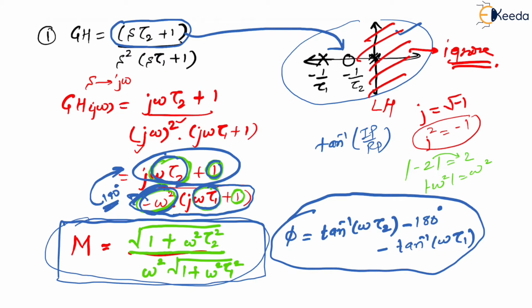So if you just see here, 0 is closer to the origin. What does that mean? If 0 is closer to the origin, it means that starting direction is anti-clockwise. If in case this pole was closer to origin, then starting direction would have been clockwise, right? So for time being, we have 0 which is closer to this origin, which means starting direction is going to be anti-clockwise.